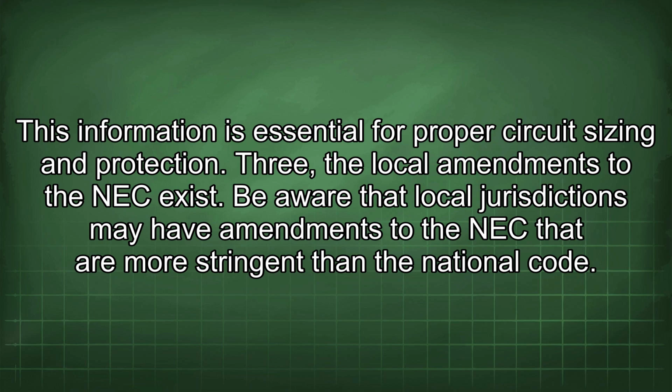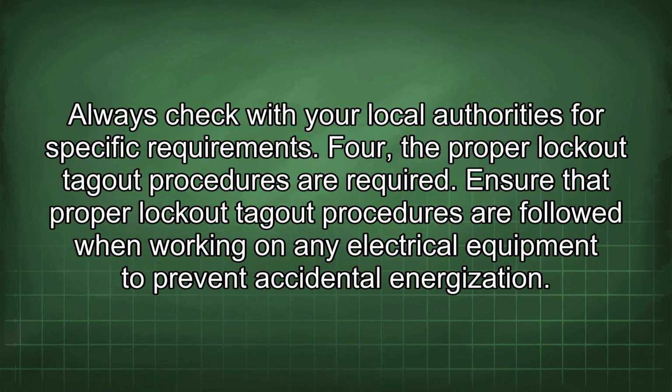3. Local amendments to the NEC exist. Be aware that local jurisdictions may have amendments to the NEC that are more stringent than the national code. Always check with your local authorities for specific requirements. 4. Proper lockout-tagout procedures are required. Ensure that proper lockout-tagout procedures are followed when working on any electrical equipment to prevent accidental energization.